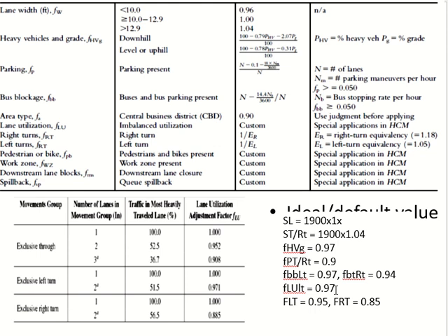And what else? Which other factor do we have? We have the work zone factor, whose calculations we did in the last chapter, but it's not given here. That's it. Now give me the adjusted saturation flow rate value. Left turning will be multiplied by 0.97.